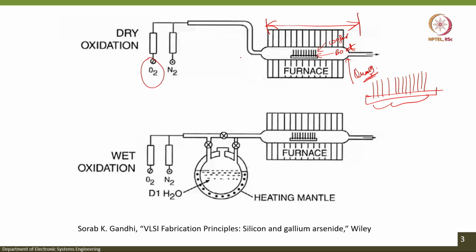It is quite evident that you need oxygen for dry oxidation, and of course, we cannot do it directly. There is something called RTP; you can't increase the temperature directly to 1200 or 1900 or something. So, you slowly increase the temperature. Meanwhile, to avoid oxidation at lower temperatures, one can use nitrogen, then slowly purge in the oxygen. That is one way. This comes under dry oxidation.